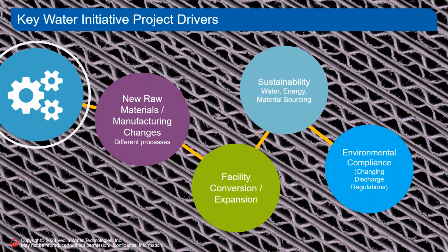The final products of these mills include recycled pulp, corrugated boxboard, fluting, linerboard, fluff, as well as tissue and toilet paper. The paper industry is a large consumer of water, consuming thousands of gallons of water per ton of paper produced. Water is used to solubilize and clean the recycled paper, enhance the characteristics of the recycled pulp through the addition of water-soluble chemistry, convey the pulp, as well as dilute it so that it forms a consistent mat on the forming section of the paper machine.